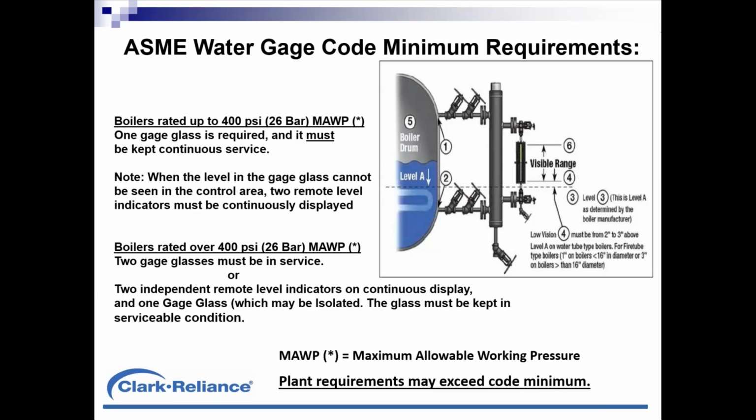In the EN standard, they state that the glass must be at least 30 millimeters below. And that's a different standard than ASME, and that's allowing the glass to encroach closer to that danger point in the bottom of the drum. So there's a bit of a difference there between PED, EN requirements and ASME. You might say the ASME requirement is a bit more conservative, giving you a larger safety bed of water below the bottom of the glass.